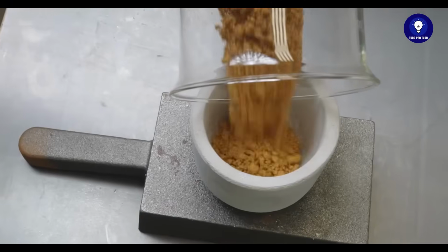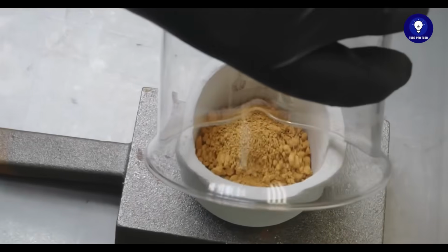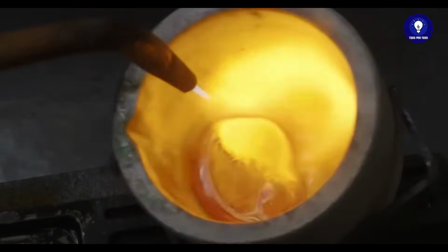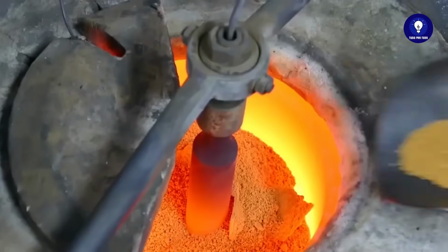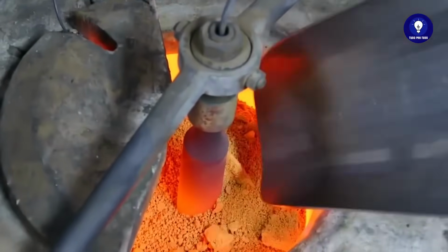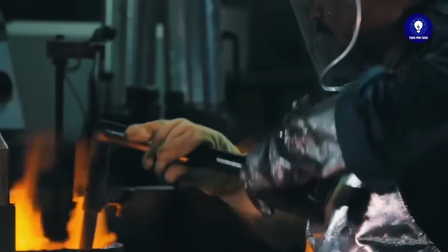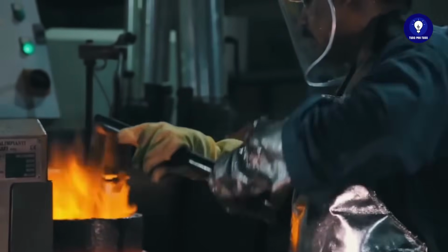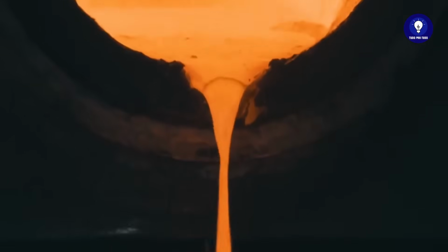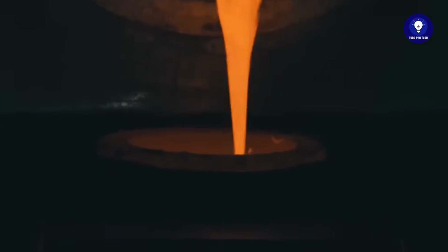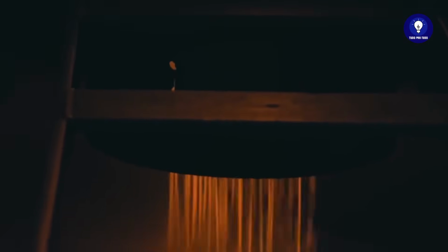The Miller process is a pyrometallurgical method that uses high temperatures. The impure gold is melted in a furnace, and chlorine gas is injected through the liquid metal. The chlorine reacts with the metallic impurities, forming chlorides that are volatile or create a slag on the surface of the molten gold. These chlorides and slags are removed, leaving behind pure gold.